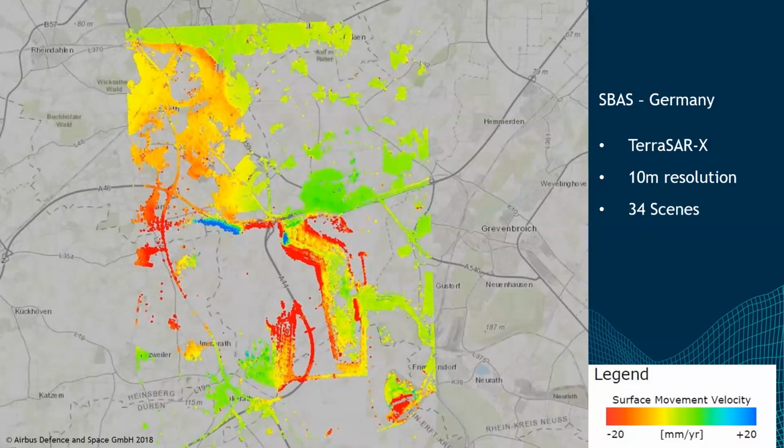As you can see, as it's been ripping away at the earth, we've got some subsidence in the local area, which in this particular case, the operator who wanted the study done is highlighting just what's going on. You can see that the northern half of the image is quite stable, and all that red is minus 20 millimetres subsidence, and that's per year. So there's a pretty rapid acceleration of subsidence.